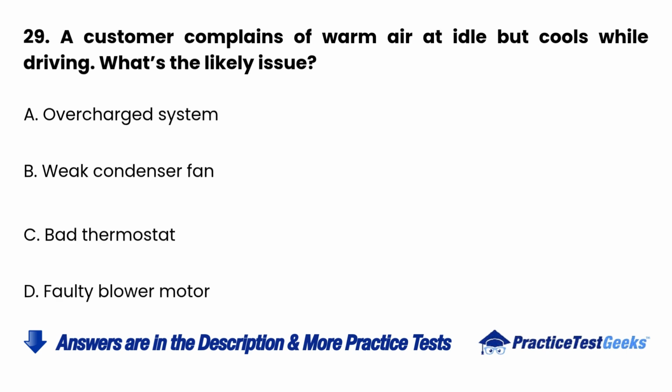29. A customer complains of warm air at idle but cools while driving. What's the likely issue? A. Overcharged system. B. Weak condenser fan. C. Bad thermostat. D. Faulty blower motor.